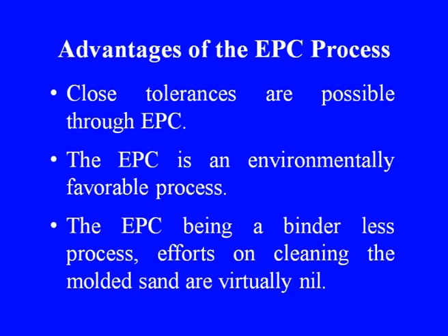Further, due to this, there is no mismatch and problems due to core shifts are also reduced. This reduces the casting defects considerably. Improved casting quality is achieved in this process. Close tolerances are possible.